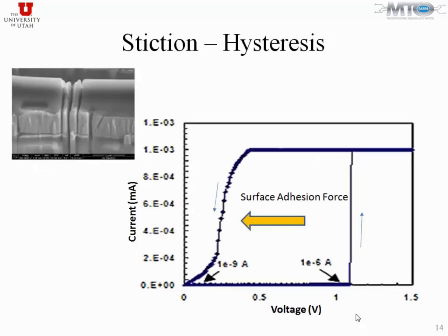So this is an example of a nanoelectromechanical switch that my group did quite a bit ago, maybe about 6 years ago, and you can see the IV is very clean, but this hysteresis is caused by the adhesion between these two cantilever beams that are vertical, and this was formed with focused ion beam.